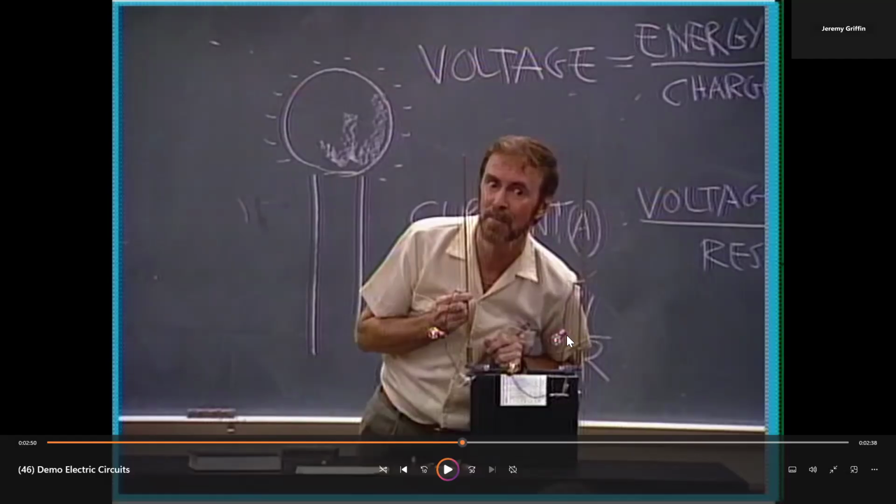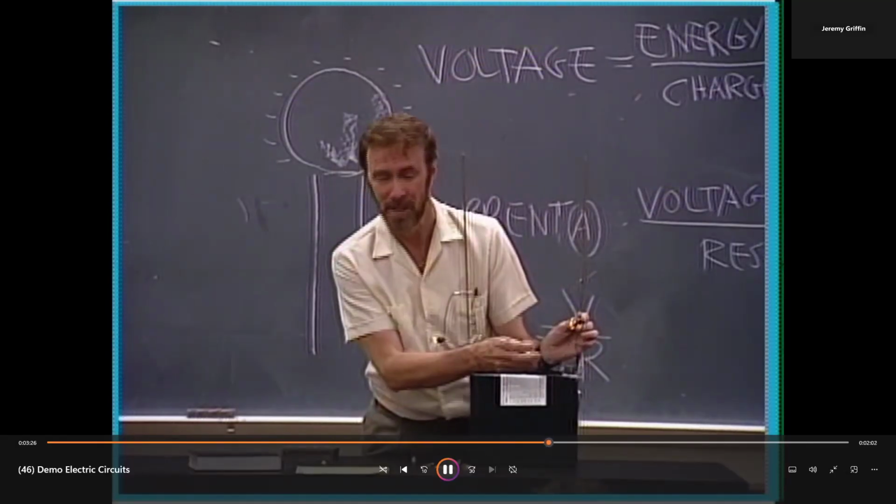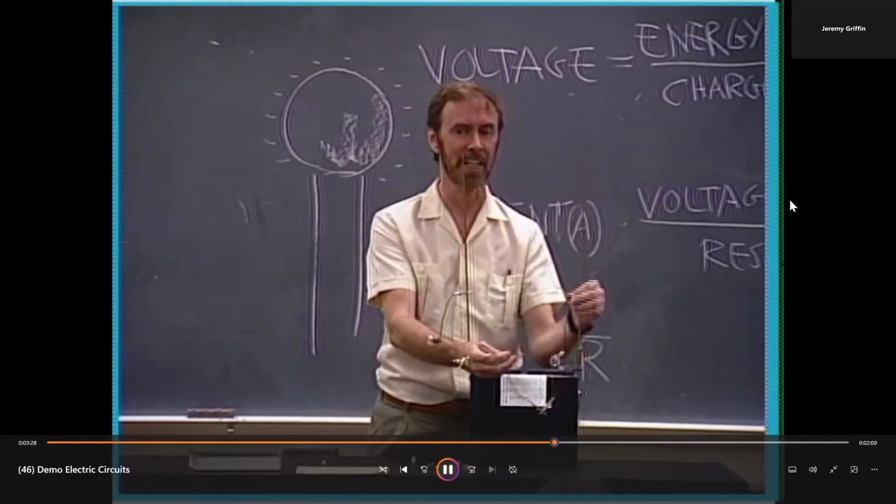All right. Now, if each bulb is 1 ohm, look at the equation on the backboard. So 4-volt drop across 1 ohm. What's the current? 4 amps, right? 4 over 1, right? You guys, is it 4 amps everywhere in that circuit? 4 amps everywhere, right? And we're looking at this from a micro point of view. We're saying what's going across each individual resistor, right? I'm going to skip ahead a little bit, right? I'll tend to, in class, explain things from a macro point of view, look at the whole circuit, and then dive into the circuit later on, right? Just so you know, look for that. Resistance getting more and more. This is a series circuit.